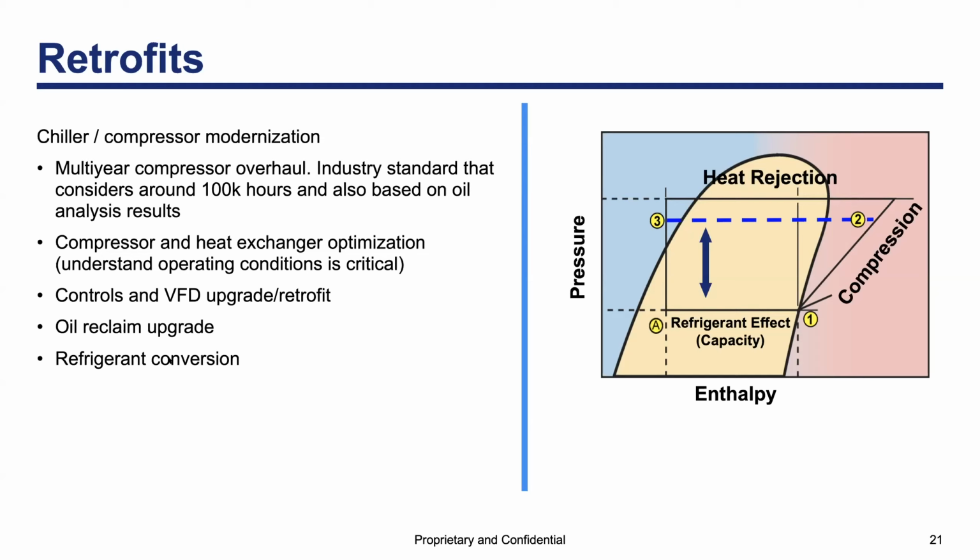That is not the case. The first and most important factor in a chiller plant is balance. The system efficiency is greatly influenced by the design conditions. And to say the same thing differently, if the design conditions are properly balanced, there is much less excess energy to be controlled out of the system. And understanding this is important.